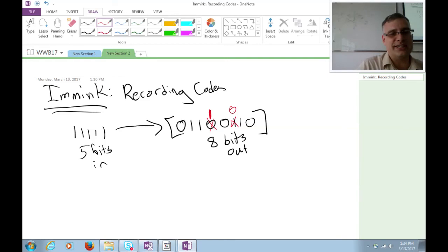And so for that reason, that almost constitutes a foolproof use of balance codes, because you can only change zeros to 1s in that medium, not the other way around. So any combination of errors will always result in a detectable code word.